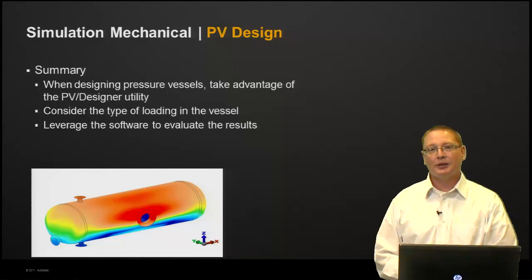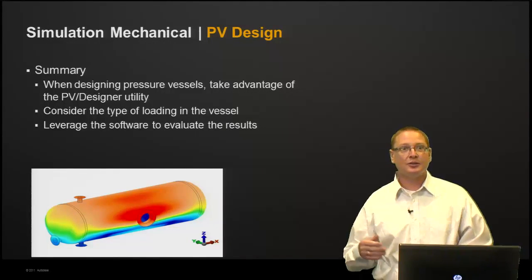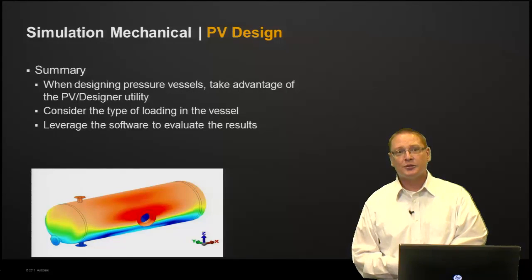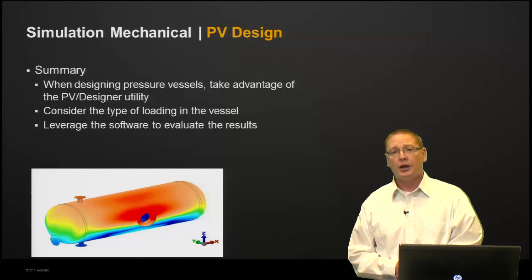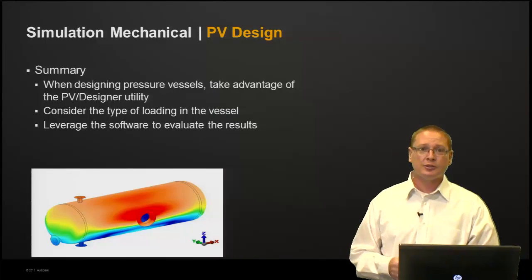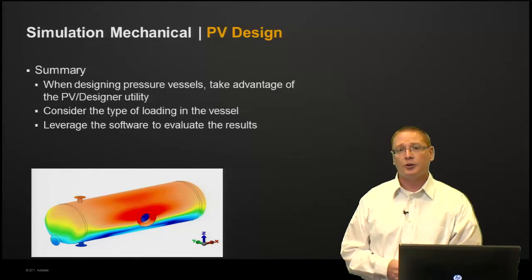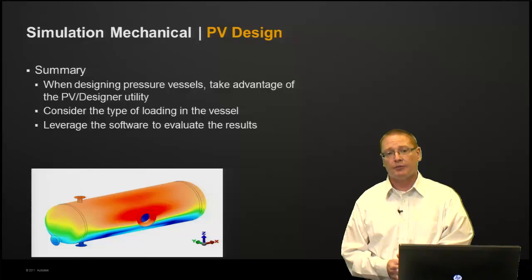Okay, now that we've completed our exercise, in summary, whenever you're designing pressure vessels, take advantage of the PV Designer utility that's within the software to help you generate that vessel. Consider the various types of loading that you have within that vessel, and then leverage the software to evaluate the results with all the different types of results options that we have available.